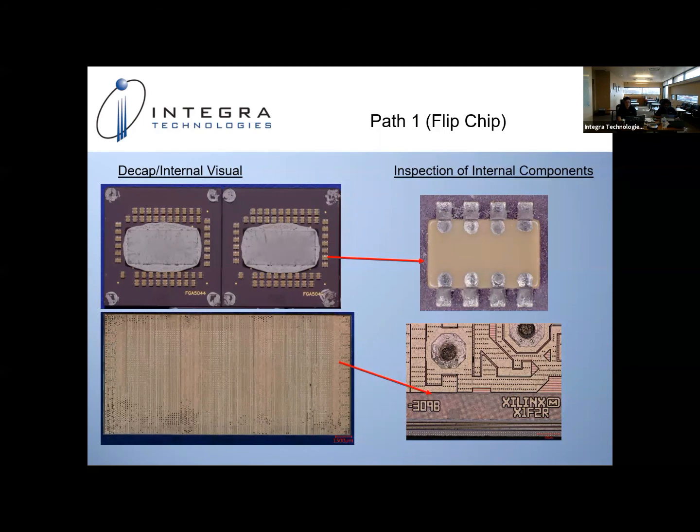Don't forget, these are called flip chips for a reason. The die is obviously flipped the opposite way. So in that top left-hand image, you're seeing the back side of the die because the active circuitry is actually still solder bumped down to that substrate.